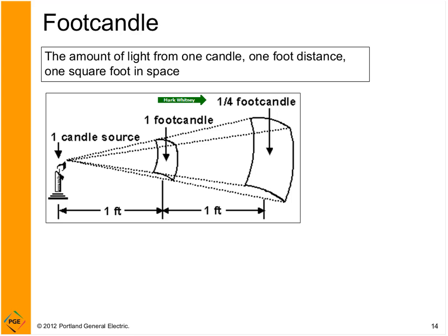And that's because light is affected by the distance squared. So very important, a 10-foot ceiling can make a lot of difference over an 8-foot ceiling, even if it's only a difference of 2 feet. Now the work plane can be your desktop, could be the floor, perhaps a whiteboard or retail display.